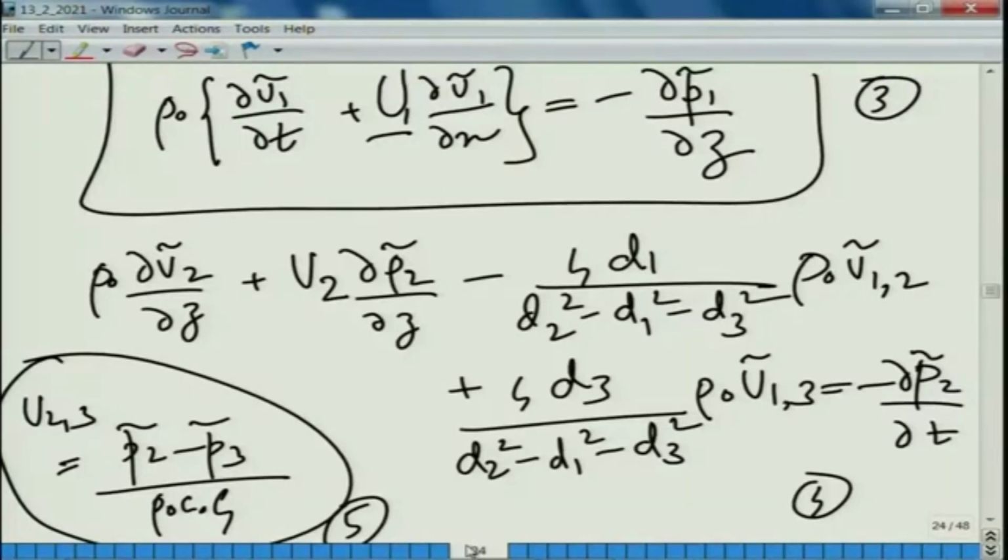It has been shown in previous papers, like there is one famous paper by Munjal and others published in about 1987 in the Journal of Sound and Vibration, where they have also ignored the convective effects of mean flow because it makes life easy. It simplifies the algebra and a lot of terms drop out, they just evaluate to 0. So, we need not consider them, but we can still account for the most important dissipative effects of mean flow, which we are going to see now by using appropriate perforate impedance expressions.